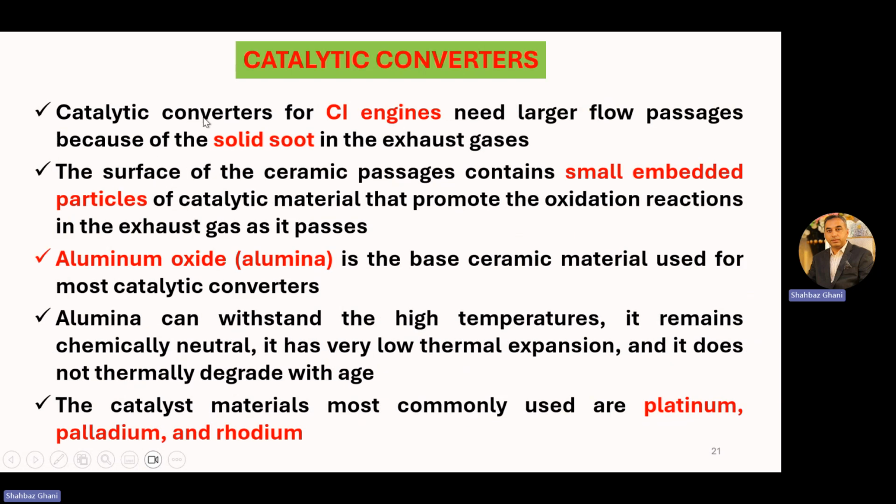Now, the catalytic converters for CI engines need larger flow passages because of the solid soot in the exhaust gases. So, another problem for the CI engine is that we need larger flow passages because of the solid particle soot. The surface of the ceramic passages contains small embedded particles of catalytic material that promotes the oxidation reaction in the exhaust gases as it passes.